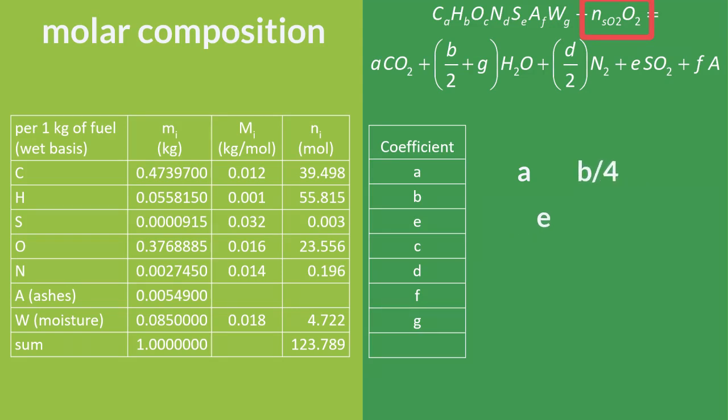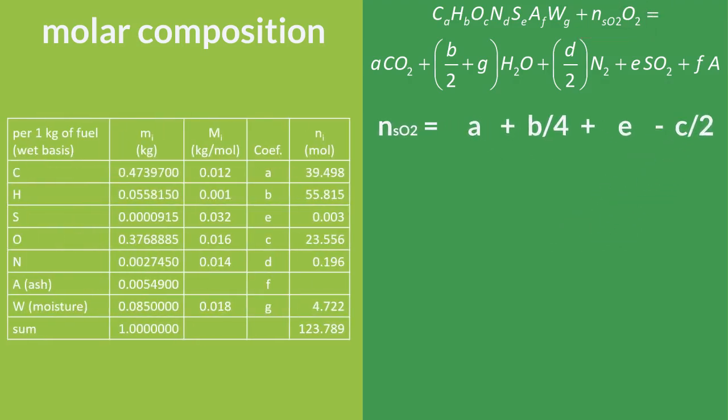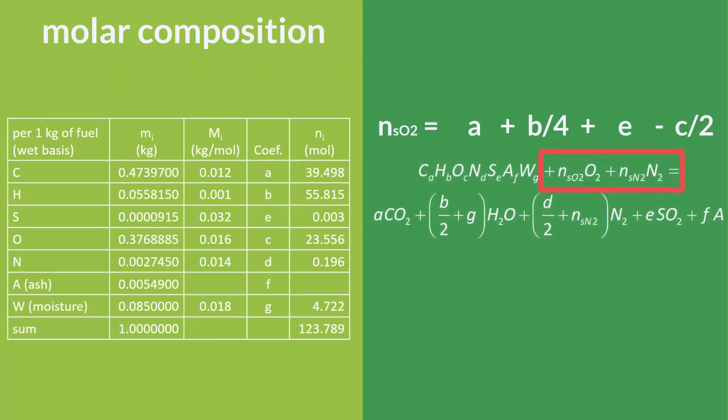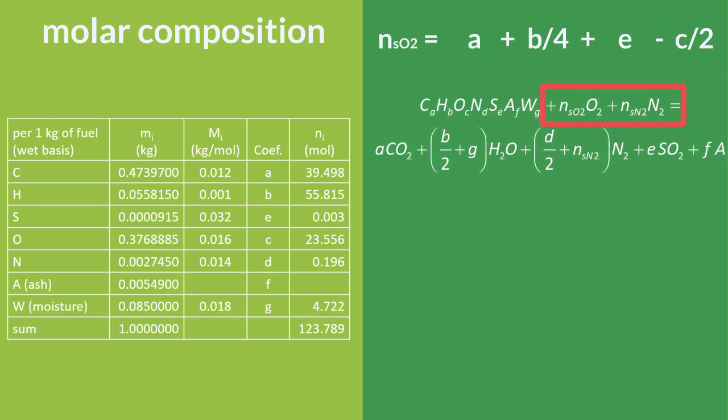The oxygen needed is the sum of the moles of carbon plus 1/4 the moles of hydrogen plus the moles of sulfur. However, we need to subtract the oxygen already present in the fuel structure. Because oxygen is fed in the combustion chamber, forming part of atmospheric air, we must calculate the stoichiometric amount of dry air for a complete combustion. This only adds atmospheric nitrogen to the formula.